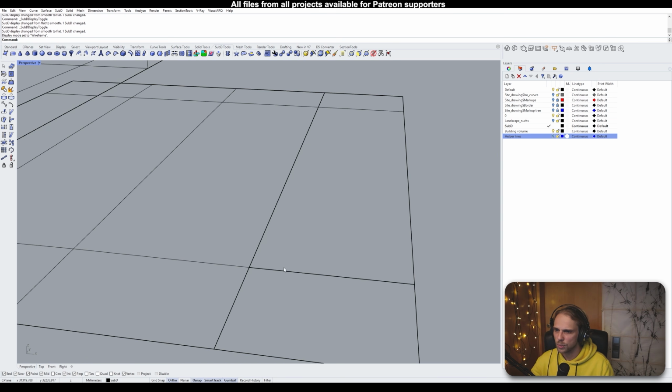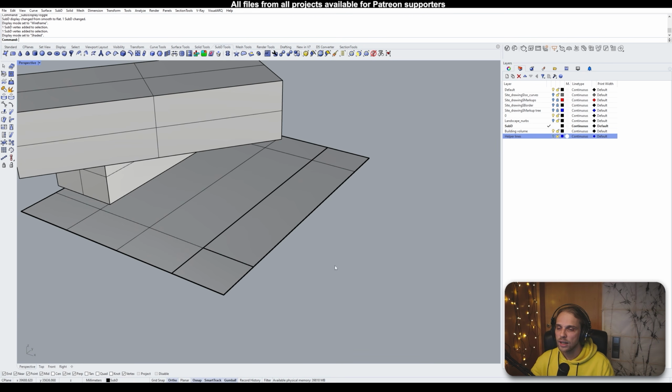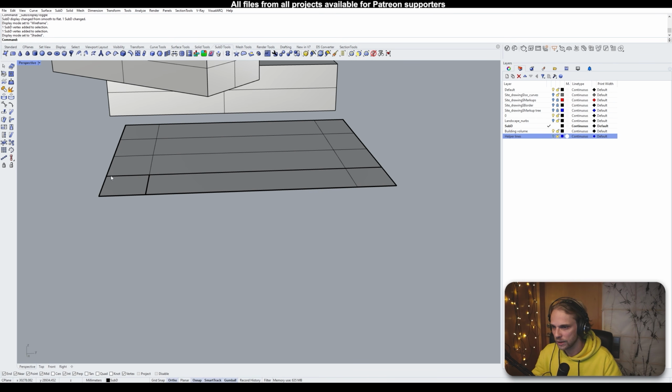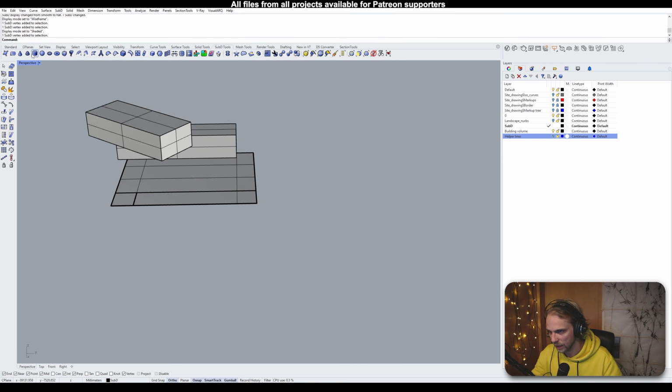Let me switch to wireframe view. Control Shift, drag around here, and it still insists on saying that it's a single sub-D vertex. So at this point, I believe that the geometry is actually clean. What is not working here is actually the creases. So sub-D can have a crease. I haven't mentioned this before, I will mention it now.